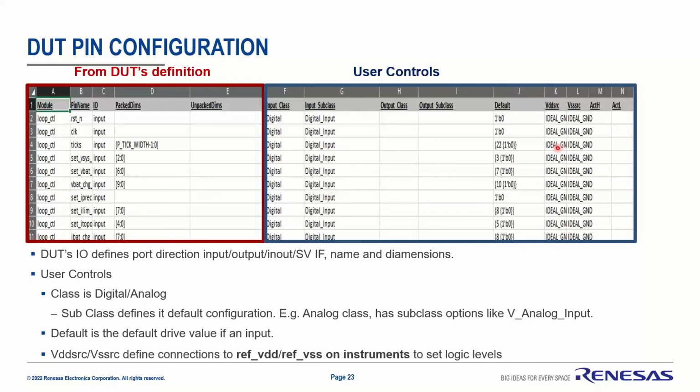Thank you. Another question. Typically, what percentage of tests from your regression suite of DMS runs do you redo with AMS? I would say ours are very mixed signal chips, so a majority of our tests are to check the interaction between the digital and the analog. So a lot of them are rerun. If I had to do a ballpark figure, I would say at least 50%, if not more.